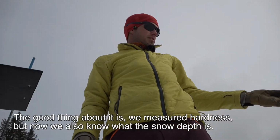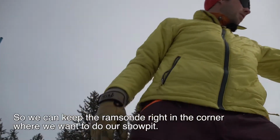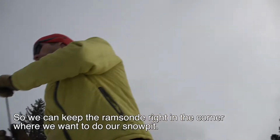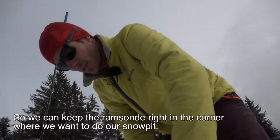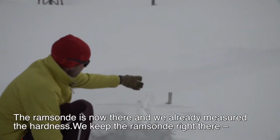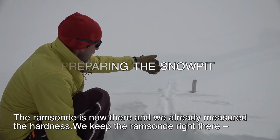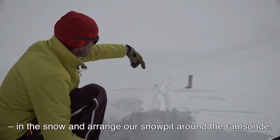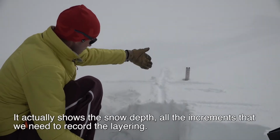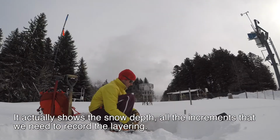The good thing about it is we measured hardness, but now we also know what the snow depth is. So we can keep the Rammsonde right in the corner where we want to do our snow pit. We already measured the hardness, and we keep the Rammsonde right there in the snow, and we want to arrange our snow pit around it, because now it actually shows the snow depth, and it also has all the increments that we need to record the layering.